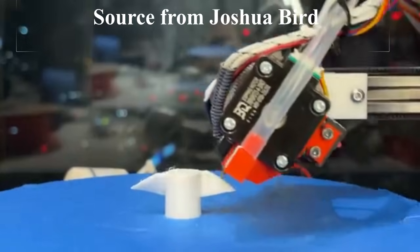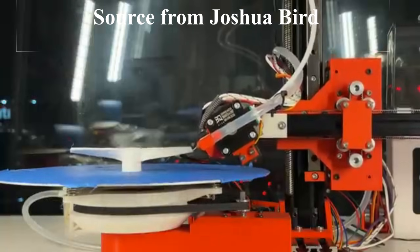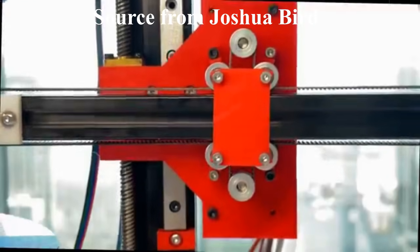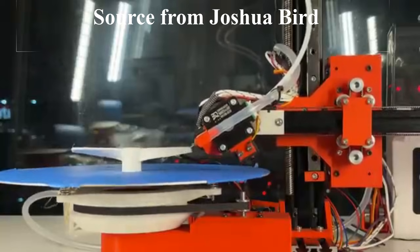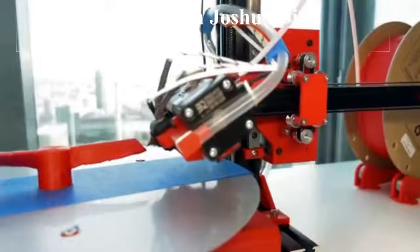So, where does that leave us? While services like JLC PCB are making 5-axis CNC machining accessible to everyone, most of us are still stuck in a 2.5D world, sanding our hands raw and peeling away waste plastic. 3-axis printing gave us complexity for free, but multi-axis printing promises functionality for free. By moving beyond the plane and embracing non-planar vector-based slicing, we stop stacking parts and start growing them. And honestly, my hands could really use the break from the sandpaper.